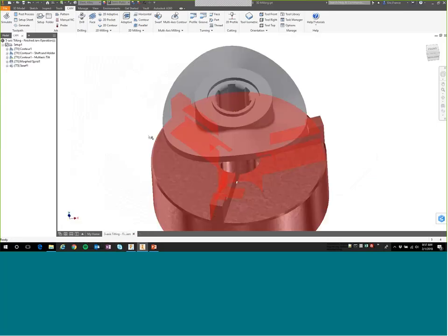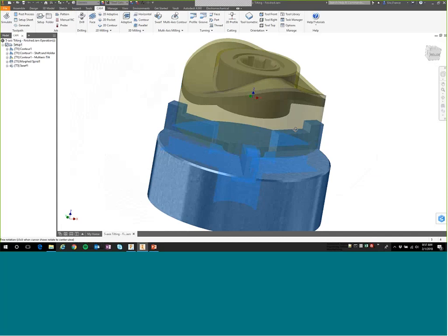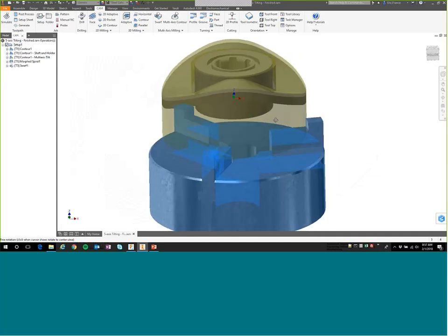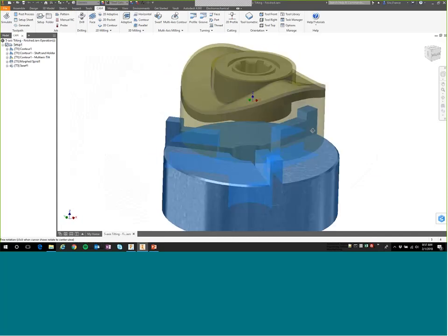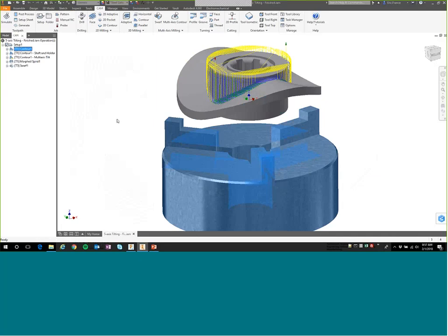All right, so over to Inventor. Let's close down that one and take a look at what we've got here. So, basically we're getting this part out. It's a casting or whatever to give us the general shape, and then we're going to do some final machining to get down to the finished size that we need. So, one of the things that you consider is doing just a 3D contour coming around the edges of this to move that in 3 dimensions.